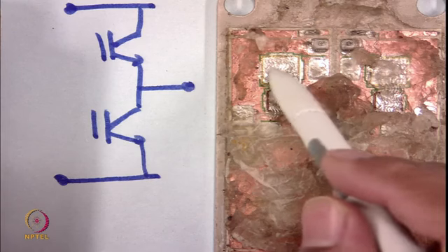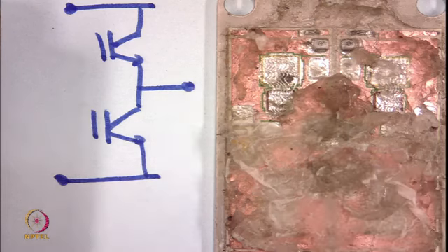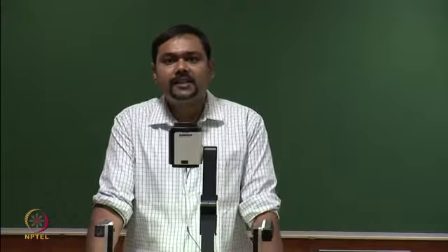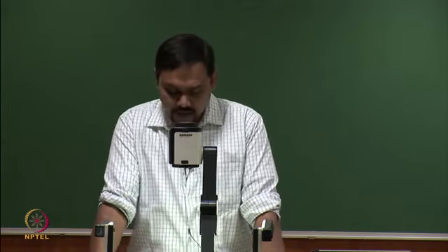For example, junction temperature in many power devices is recommended to be around 150 degrees. Junction temperature will be the temperature inside here, whereas case temperature in many cases is recommended to be close to between 60 to 70 degrees maximum. It should be less than that if possible.